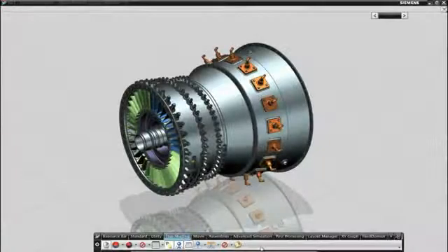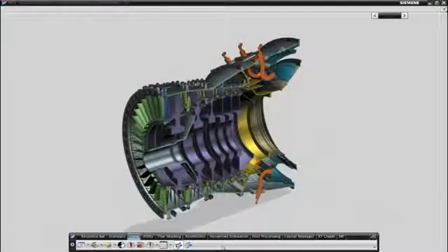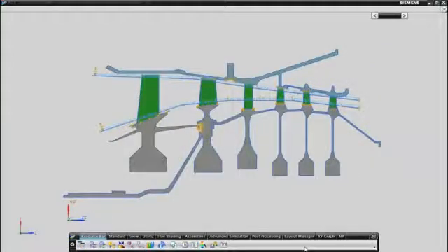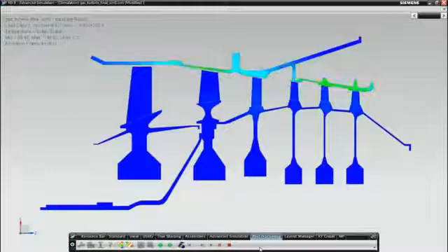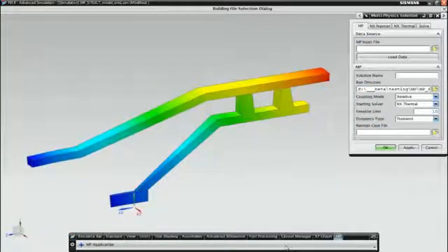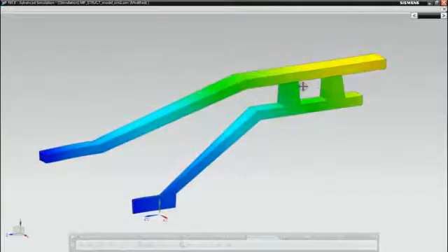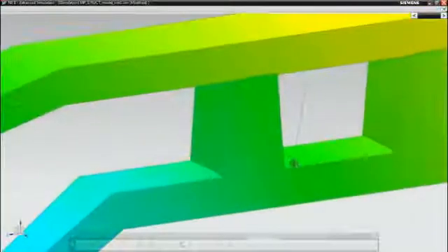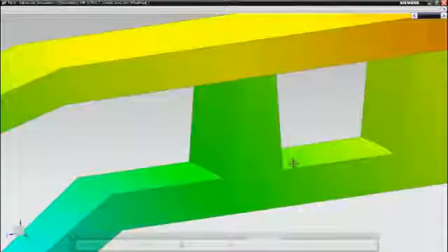In the areas of thermal and structural analysis, NX CAE introduces the ability to conduct multiphysics thermal mechanical analysis by coupling NX Thermal with NX Nastran. Coupling is made easy within the integrated environment and eliminates data transfer errors. This is useful to analyze thermal contact problems that will also have impact on structural performance, such as an aero engine design for the seal and casing. The results here show bending of the structure due to thermal loads, which then also affects heat transfer as a seal comes into contact with the casing.